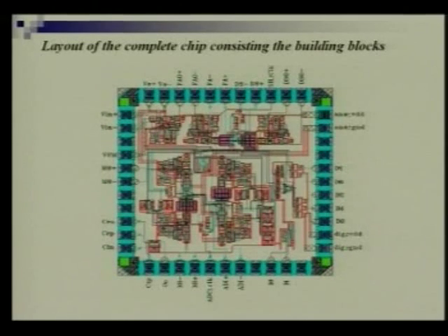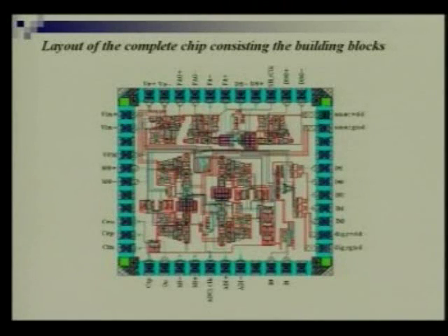And another thing: whenever you are doing analog design, every time try to use differential mode from the input to the end. Suppose you are giving some clock, make it differential. In any ADC design, you need a lot of digital part and also some analog part. It's not that only analog will be able to do the analog chip. These are basically mixed-signal chips. So you will have to be very careful from the beginning to the end, and try to have a differential type of architecture all the time, which will make your life much simpler, okay? Because so far as noise analysis is concerned too.